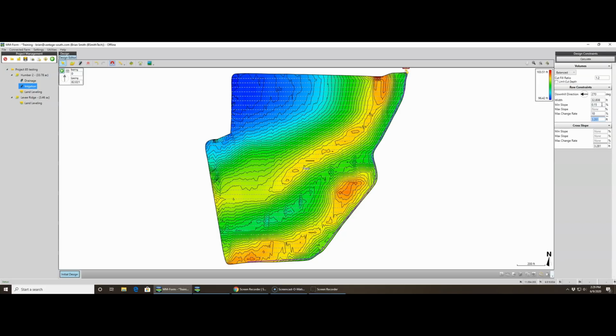Then we want to tell it how many feet we will let it fall that 10%. Okay. So 100, well, let's just back up. 10 feet would be the least amount of smoothing. 50 would be more, 100 would be more, all the way up to 300. 300 is about the most you will get. This downhill direction, generally, I just put on 10 and 100. That's just a generic number or a default number that I just put in, okay?